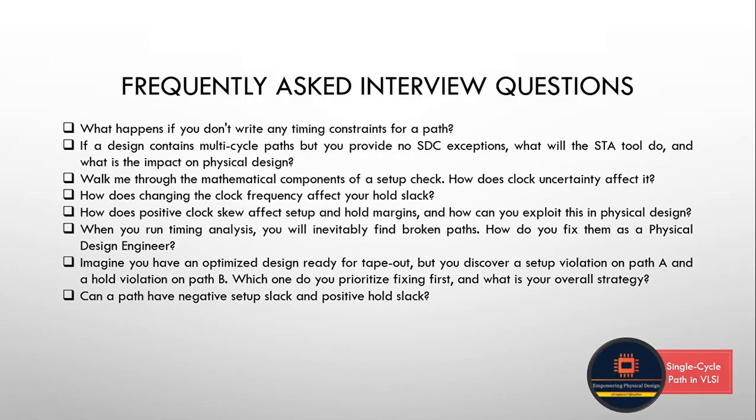Okay. I'll explain this particular question in a separate video. I know it's not so easy to explain. I'll make a separate video on how the uncertainty affects both setup and hold. Just as a rough answer, it basically reduces your setup slack because it subtracts from the required time. Okay, that's it.